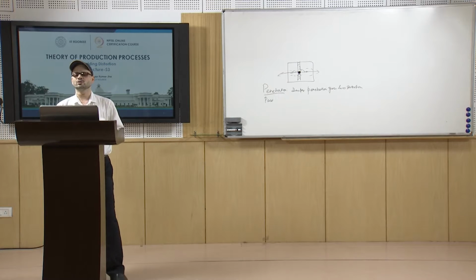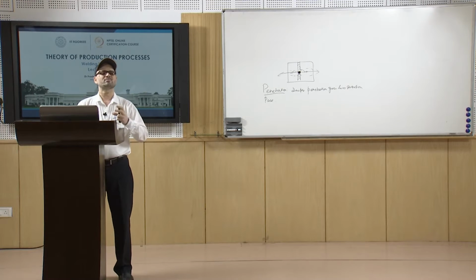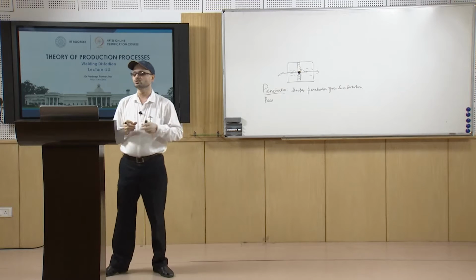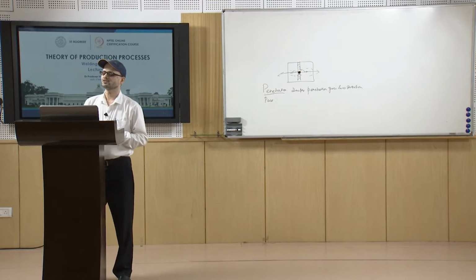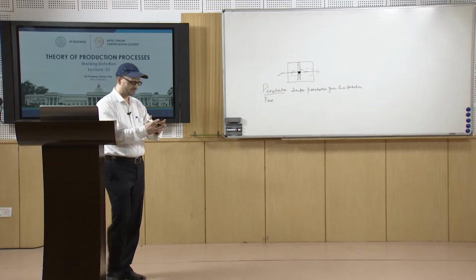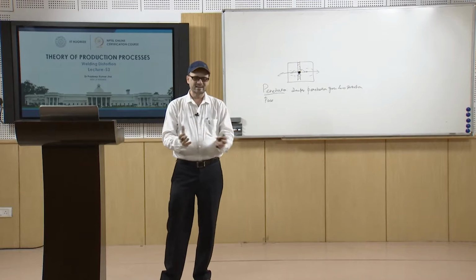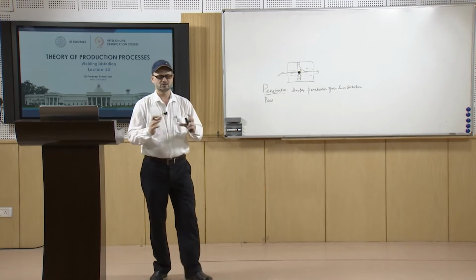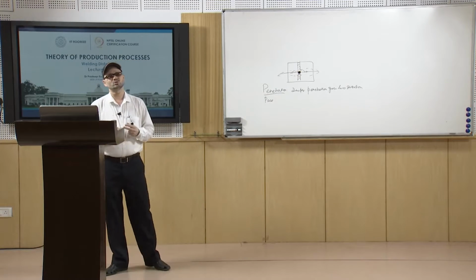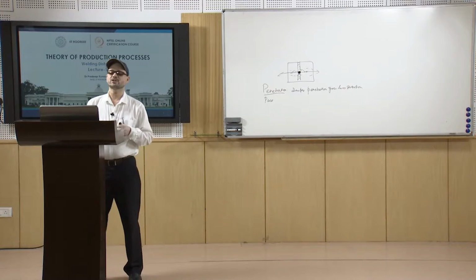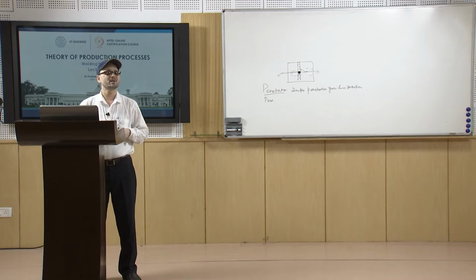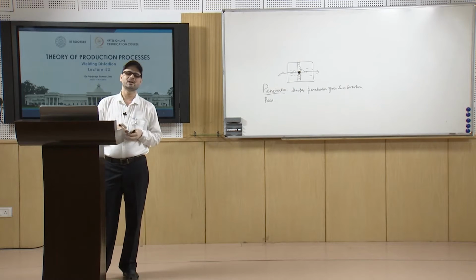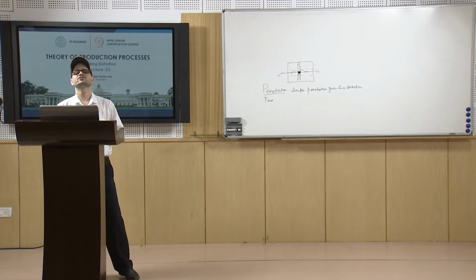Also, when you have a close fit up of the joint, it will reduce the stresses. If a close fit up is not there, then more weld metal will be there in that zone. So, that will further lead to an increase in the stress value. So, close fit up is also necessary for decreasing the value of the residual stresses.